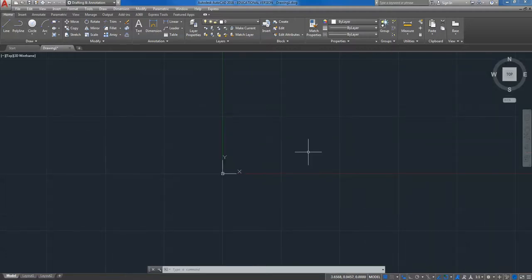Just remember the point entry command, or a point entry with the line command. You can either do polar, relative, or absolute coordinates. Just recall that in polar coordinates, you need the @ symbol and the less than symbol. For the relative coordinates, you need the @ symbol. And for the absolute coordinates, you need the hashtag or the pound sign, okay? That's when the dynamic input is on. When it's off, it's going to always go to absolute, okay?